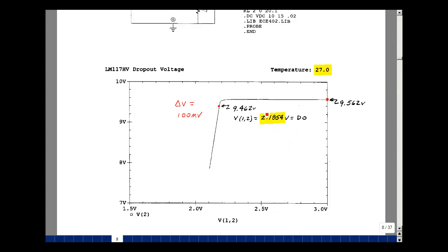Now this won't agree with the data sheet super closely, but again, this matched my lab data. And so I was following my modeling based on what I could measure. Very hard in a data sheet. Sometimes they don't show you all the test circuits, and you don't know exactly what they did when they took the measurement. And I got a little bit frustrated with the fact that I couldn't make my model fit the data sheet, and then I decided to just build everything and see how it turned out.